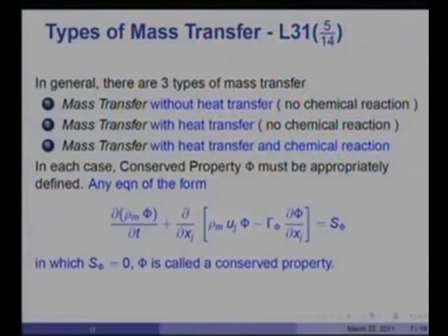So, positive mass transfer takes place even when heat transfer is to the transferred substance or from the transferred substance to the considered phase. In other words, heat and mass transfer are simultaneously occurring, but they can be opposed or aiding each other. We consider this to be the situation of inert mass transfer with heat transfer, but no chemical reaction.